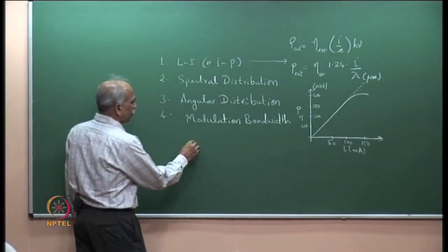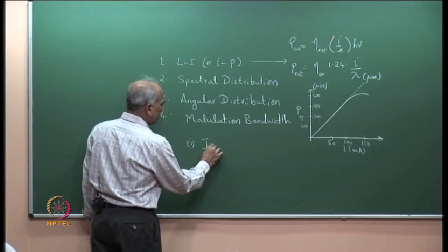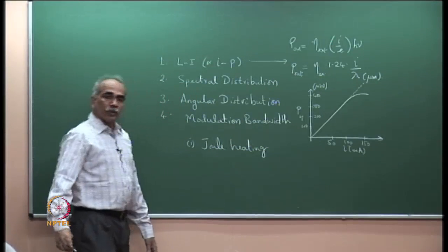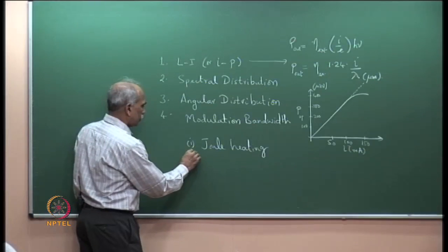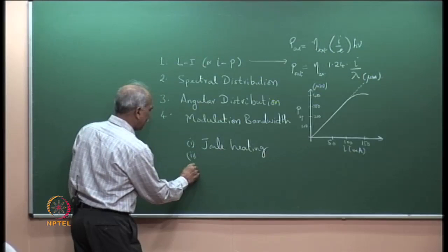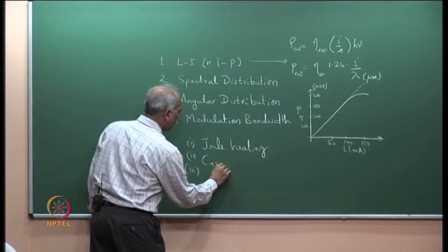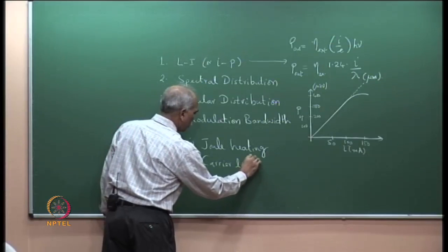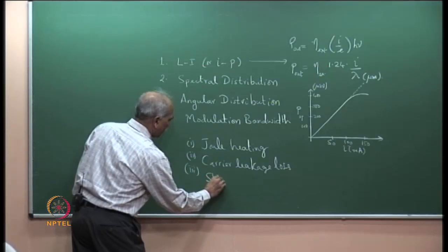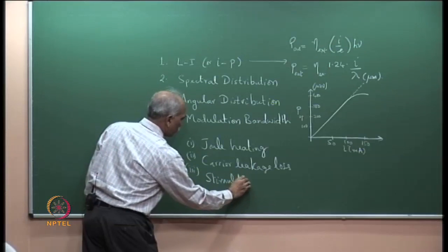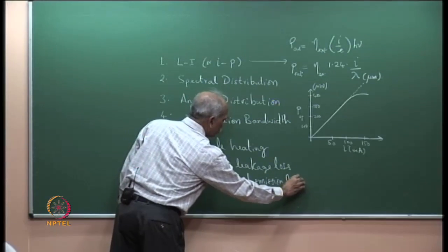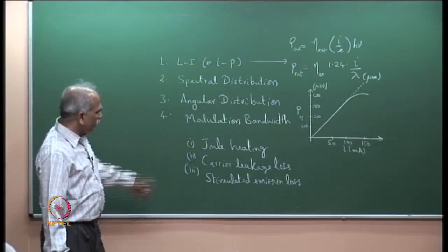I had listed three different reasons. One, the Joule heating. I am quickly recalling what we had discussed. Second, carrier leakage loss. And the third one is stimulated emission loss. So these are the three major reasons.